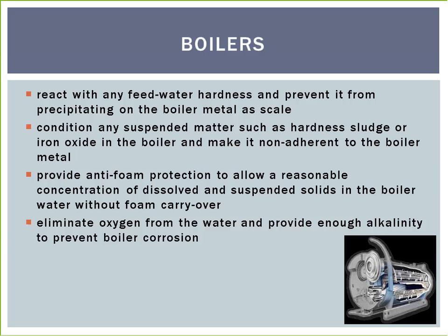corrosion. In addition, as supplementary measures, an internal treatment should prevent corrosion and scaling of the feed water system and protect against corrosion in the steam condensate systems. For the water treatment program, specific doses of conditioning products are added to the water. The commonly used products include